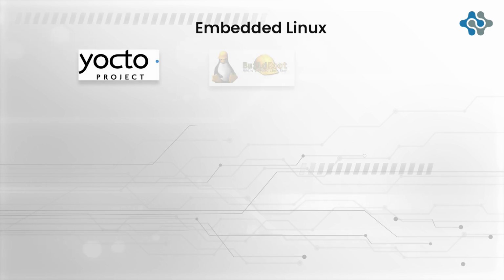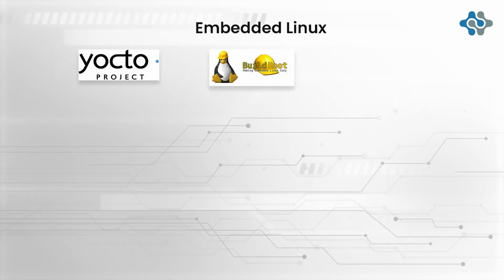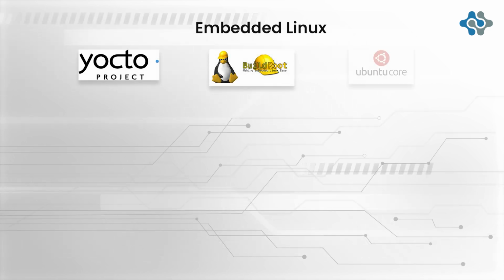The primary players you encounter for MPU-based embedded developments are embedded Linux. This is probably the most common choice today. It's a full-fledged Linux kernel tailored for your specific hardware using build systems like Yocto Project, Buildroot, or customized distribution images like Ubuntu Core. Why choose it?